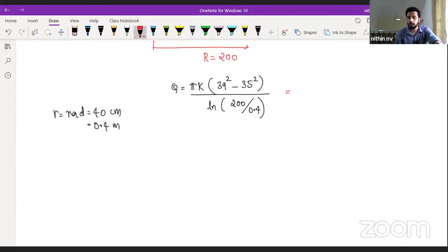Yes, very good. Coefficient of transmissibility or coefficient of transmissivity is nothing but K into thickness of the aquifer. In general, I can simply put it as K into H only here, where H is the thickness of aquifer. B is what we keep in a confined aquifer, that's why I have kept it as B. This is for confined aquifer. This is for unconfined. H and B are the same only.